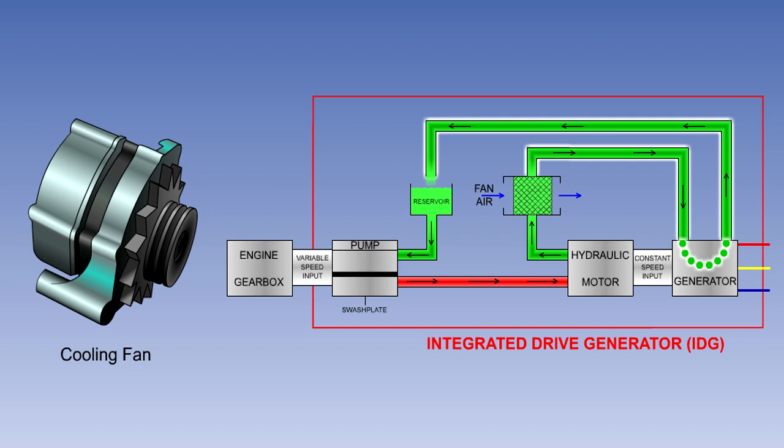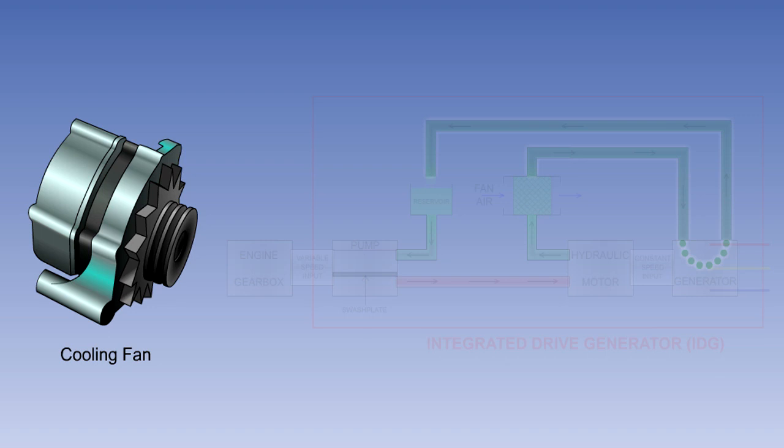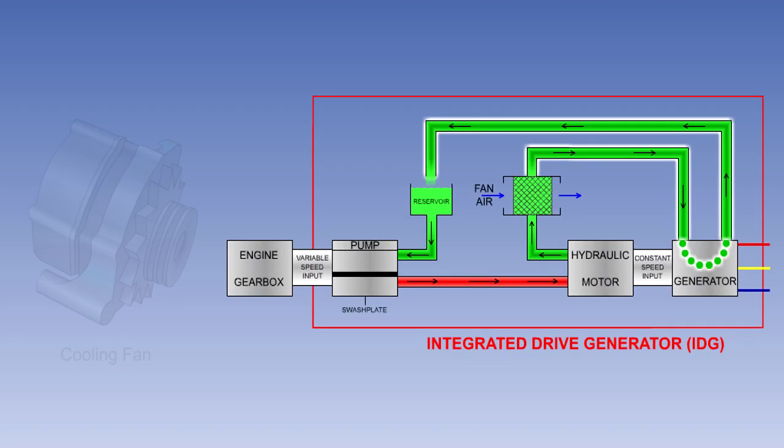There is a great deal of heat generated in a generator's stator windings due to the current flow through them, and some form of cooling system is required. Frequency-wild generators, or constant frequency generators with separate constant speed drive units, typically use ram air cooling in flight, and some means, such as a mechanical impeller, to induce airflow on the ground. Integrated drive generators use the oil from the speed control system to cool the stators. The oil is cooled in its own oil cooler.